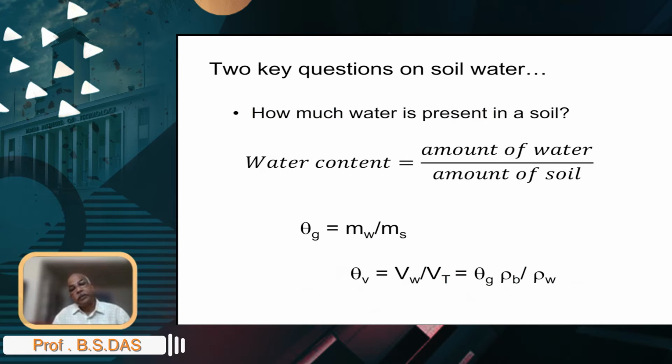So an inherent, intrinsic quantity for the soil wetness will not be possible. And so it's always mass of water divided by mass of the oven dry soil, which does not contain any water. And to get soil wetness in terms of volume basis, you basically multiply the gravimetric water content with the ratio of the bulk density to the density of water, right?